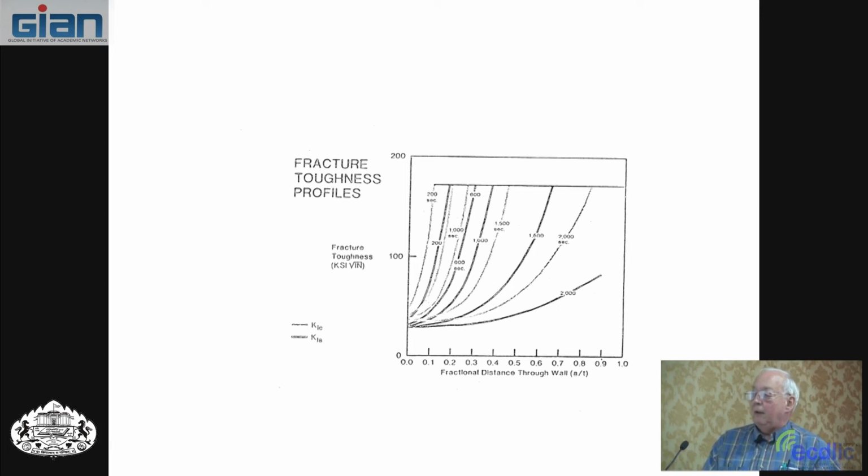That is, if a crack starts to run but then hits a tougher area, it should stop. So there's K1C for initiation, K1 arrest for stopping. And the K1 arrest line is behind the K1C line. But because the material's changing temperature, this transition changes with temperature.